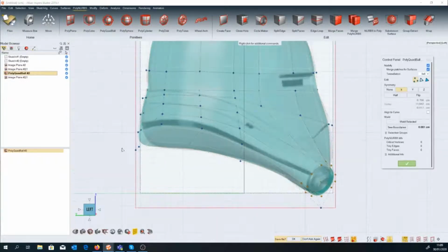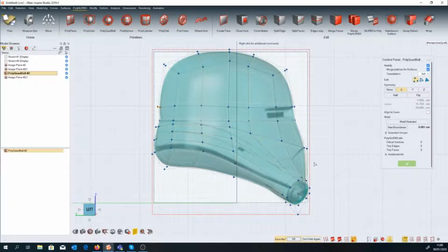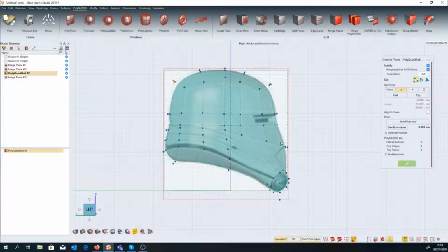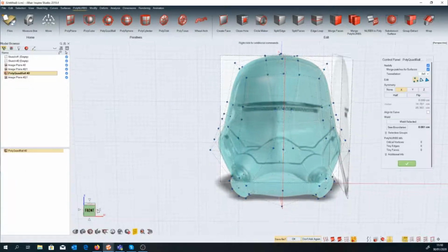I used the three levels of editing of the PolyNurbs: vertices, edges, and faces. All these geometries can be modified by the manipulator tool. You can move, scale, and rotate. You can also slide some vertices along an edge.